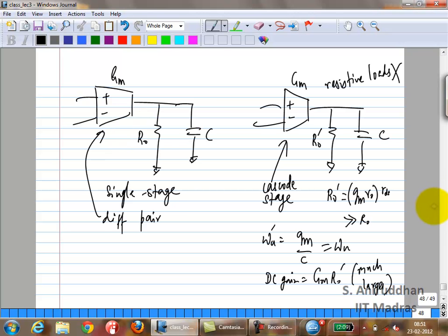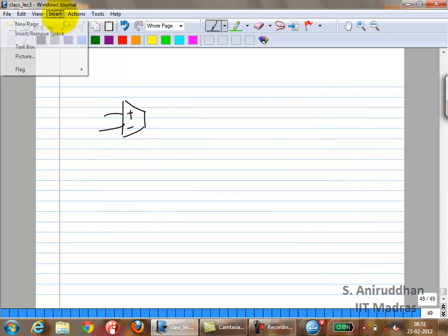So this is just a cascode op amp, just a single stage. Same thing, you have the diff pair, you had a cascode for the NMOS, cascode for the PMOS. Right? Because you want to increase the output impedance. Correct? So it looks something like this.